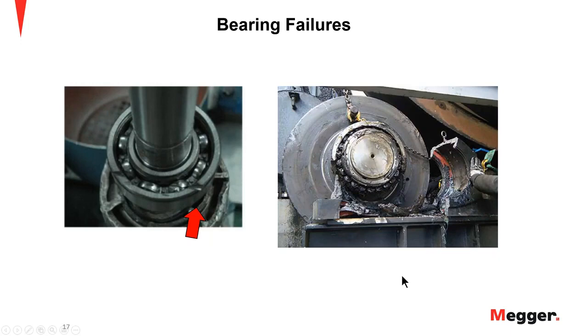Bearing failures, with this being at the top of the list. You can see in this image that something has gouged the external piece of this bearing. It could have been something that broke off internal to the motor, or something that wasn't aligned properly, but something really took a hit inside and gouged the inside of this bearing. So that would be a replacement job, of course.